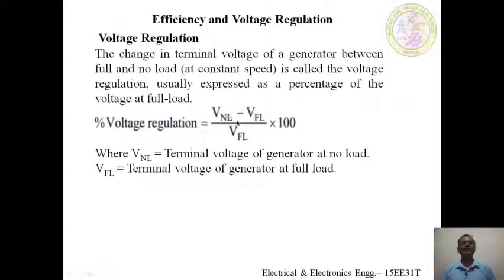You know that as load increases, voltage drops. That is, the voltage will change from no load to full load. If you express that change in voltage in terms of full load voltage, then we will get the regulation of the generator.